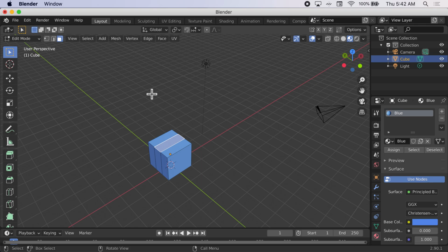We're going to use this new word called extrude, which means to kind of pull out a shape from like this 2-dimensional side. If you want to look at it as kind of like this cross section, we're going to pull it out from a 2-dimensional cross section into 3 dimensions. So as we do that, we are going to evoke the extrude tool by pressing E for extrude. We're going to extrude in the Z direction by 3. So the commands are going to be E, Z, 3.